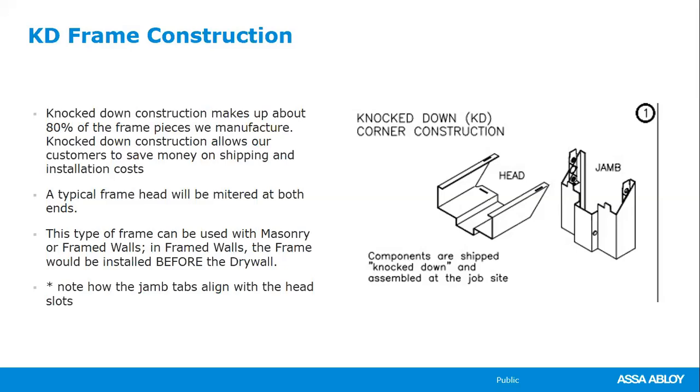And the reason is, throughout years and years, a lot of these frames were shipped out to the job site. The installer had to be someone who really understood metal frames, installing in the proper way, bending the tabs the proper way. What we found was a lot of times these frames were not being installed correctly. The miter corner had a gap between your head and your jam. If that masonry frame is installed, unless you're going to rip it out of that wall, there's really no way to fix that. So over the years, basically the industry has gone to a masonry frame that goes out to the job site with its corners welded.